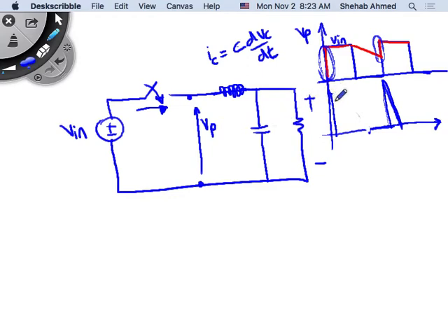Right? So the capacitor current actually also has to be fed, but you charge the capacitor during a period of time, then the capacitor current is zero, right, until here, and then the capacitor is now discharging to the resistor, right? This is what the capacitor current would look like. Charging the capacitor, then it's zero, then you are feeding the load again. That's what the capacitor current would look like in this case. But now I've eliminated these high spikes and done my job by adding this inductor here.